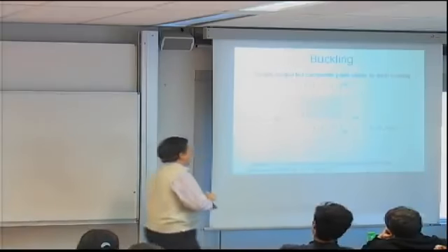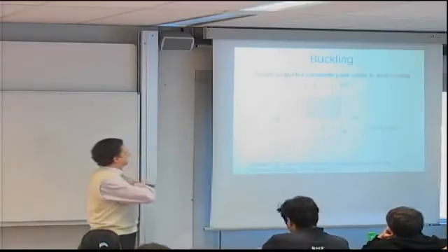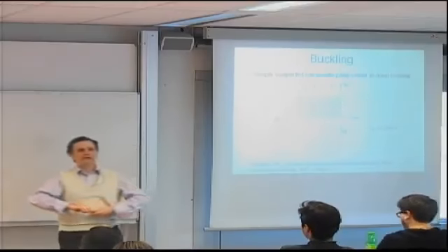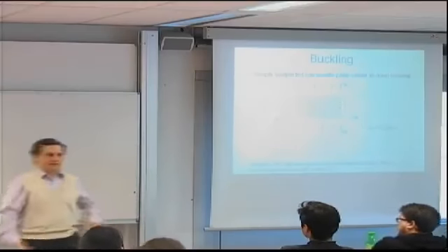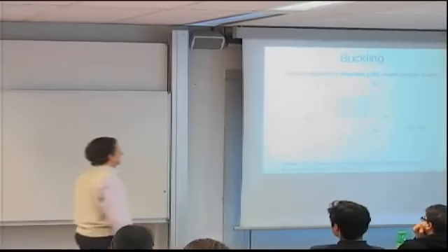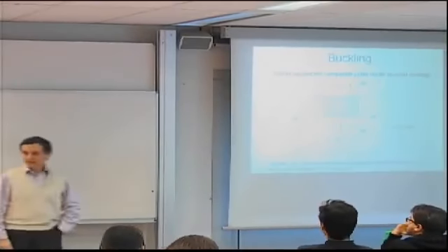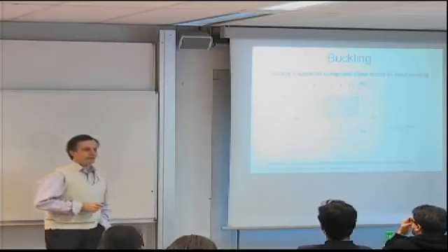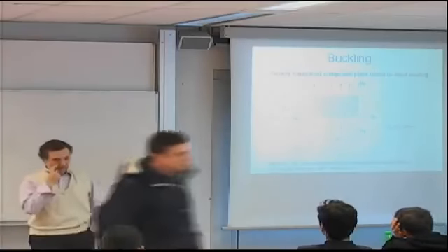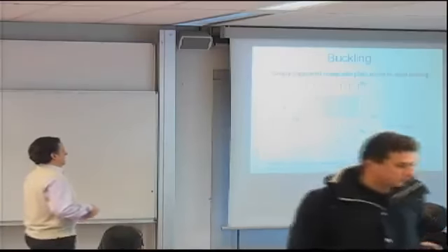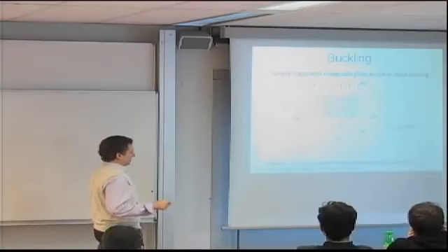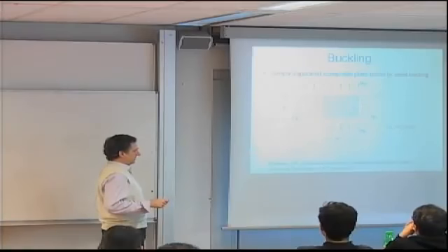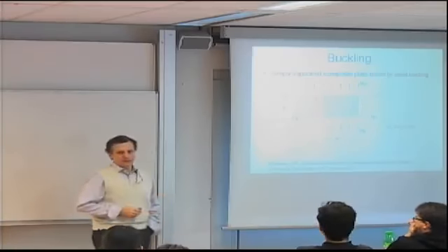We had started talking about buckling of plates. And as an example that is general enough and that will allow us to find other cases as special cases, we dealt with a biaxially loaded plate, and we said at least one of the loads must be compressive. For ease of calculations, we assumed D16 and D26 is 0, and the B matrix is also 0.